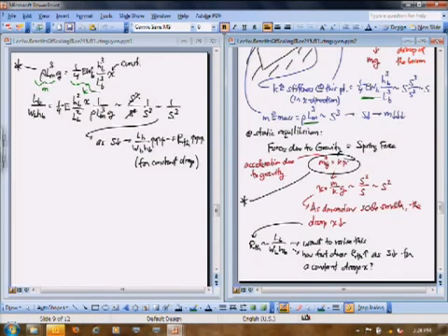Why in essence do you want RTH to go up? You want RTH to go up to maintain it at temperature. There's one thing of getting to temperature, but there's the other one about how much power you put in to get to temperature. So it took 1 watt for that 3 centimeter by 3 centimeter cell physics package that I looked at. It took 1 milliwatt, 2 milliwatts or so for the tiny version. So many orders of magnitude smaller power. So you end up winning in everything. It's one of the nicest scaling things that we find. All right, so that's the atomic clock argument here.